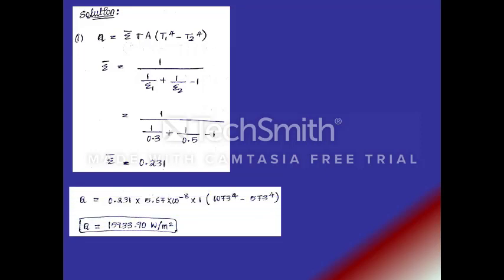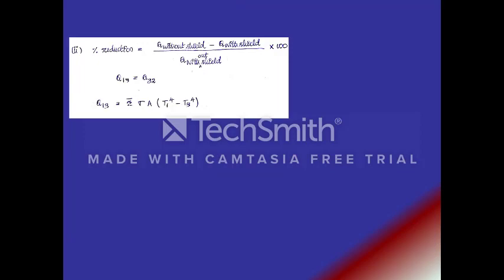Now you substitute the value of epsilon bar and you can find out the heat transfer as 15,933.90 watts per meter square. This is the heat exchange between the two plates in the absence of radiation shield. Now we will proceed to calculate heat transfer in the presence of shield.